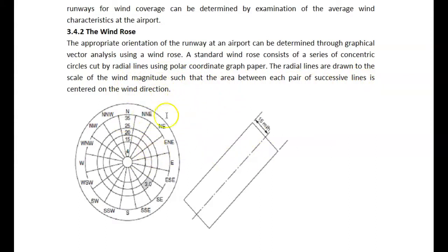So when you place this on here, or you impose it on here, you'll be able to measure the direction of wind from different directions. You'll be able to get that, because this transparent plate or template placed here makes visible the things that are calibrated in these circles. So these circles, like I said, are the magnitude of the wind.